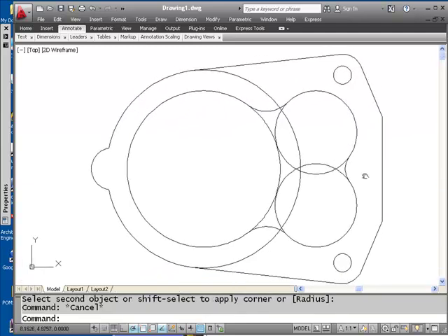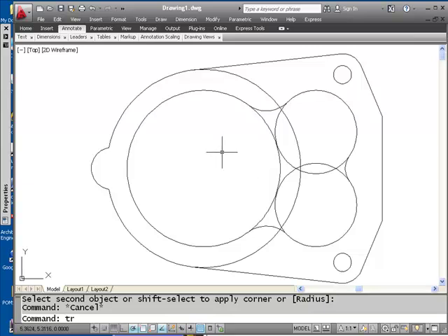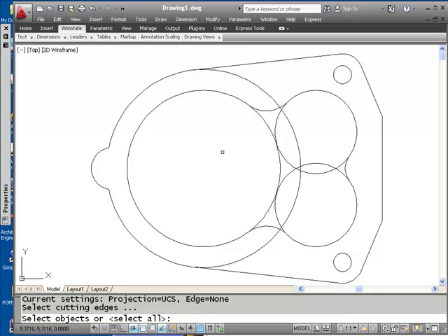And now before I do any trimming, I'm going to select my cut lines. Here's a place where a lot of people would make a mistake. They would type TR for trim and then just hit the enter key to select every line as a trim line. But you have so many lines here that if you do that, the chances of leaving behind some small segment of line that you will ultimately snap to when you don't intend to, creating an error in the geometry, it's a bad idea.